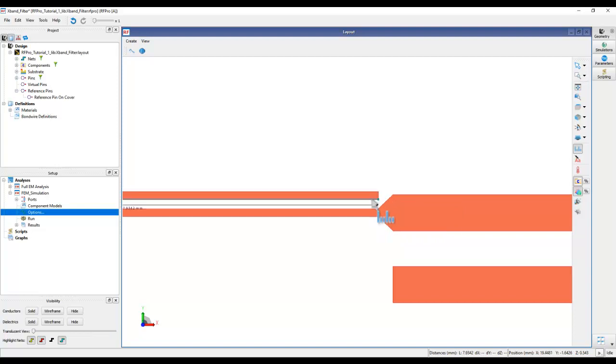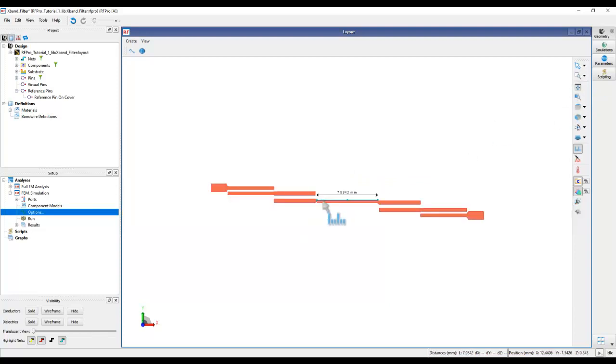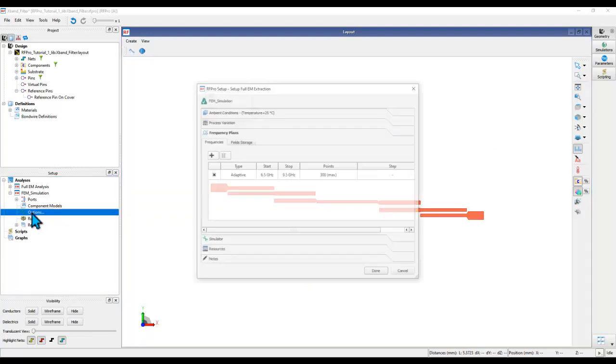So if I want three mesh elements across the width of this line, I select the edge mesh to be 0.03 mm, which will create a pretty nice looking mesh in this coupled structure to make sure the results are appropriate. That's the only setting I need to do.